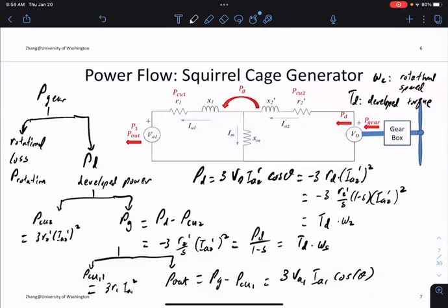In the equation, whenever you have the current square, is that always the magnitude of the complex square? Yes, you're right, so that's a good point to emphasize. Anytime you see IA here, that's a magnitude. Especially when you see IA square, we're squaring the magnitude. We're not squaring a complex number. It's a magnitude square, because PD has to come out as a real number. It has to be a real number.